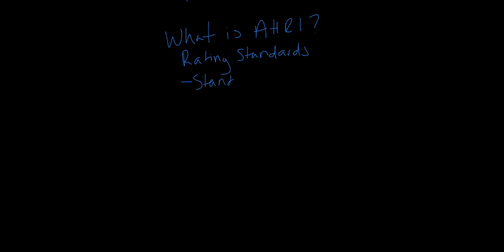Now we look at standards from a different society. AHRI. What is AHRI? Which stands for Air Conditioning, Heating, and Refrigeration Institute. AHRI covers what are called rating standards. With those standards, we include Standard 410. This standard rates the performance of heating and cooling coils.